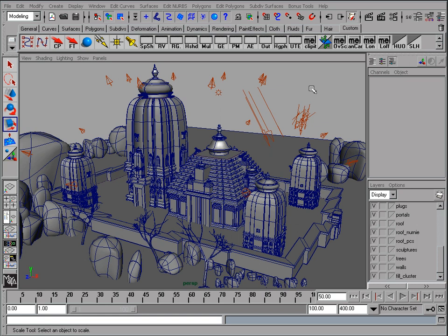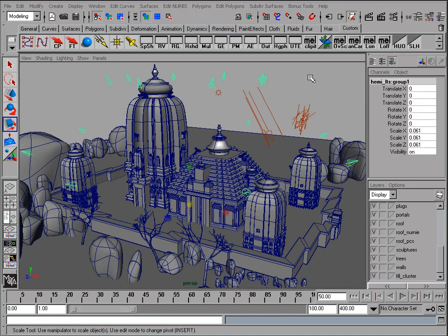So the next step up from this technique is to use a light dome. And this is nothing more than a hemispherical collection of spotlights and or directionals. There's a great MEL script for this, GI Joe, available from Highend3D, which automates this. What I do for basic lighting studies is I keep around a kit of 16 of these lights, and I import this in as a group.